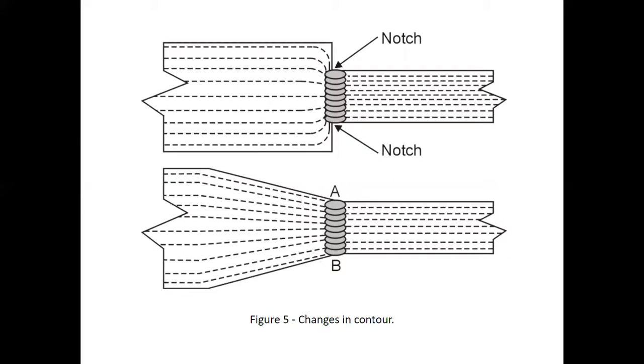So this here is kind of showing the connection of 2 pieces together. We have a smaller bar connected to a bigger bar, and you can weld them. This is basically just a straight butt weld. That can work. It can be done. If it is seeing stress and has some dynamic movement to it, that means seeing forces, compressive and stretching forces, then we want to taper it back.